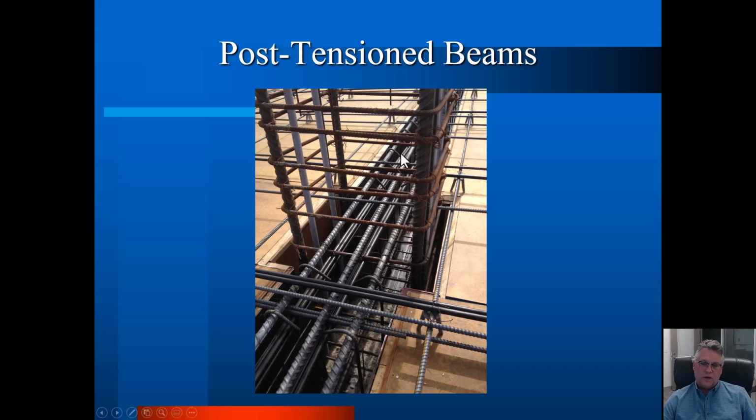This is a different job. In this case, the supplier has black sheathing around the strand. In post-tension concrete, the strand itself, the strand is the metal that we're going to see in a future slide. But it's inside, it is greased, and it's inside this plastic. And the idea in unbonded post-tension concrete, cast in place unbonded post-tension concrete, is that the pre-stressing steel is never in contact with the concrete.